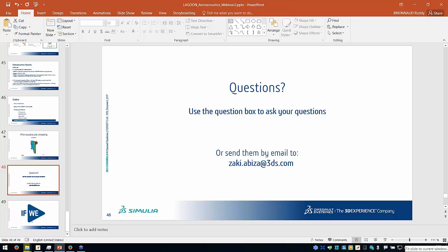So the first question: can XFlow perform acoustics analysis in water? Okay, so I've been speaking about air, for example, but as you've seen, it's very easy for XFlow to adjust the speed of sound. The only difference between air and water is actually the compressibility and speed of sound of your fluid. Typically with air you've got 340 meters per second, and for water you would have 1400 meters per second. So the equation that relates the lattice spacing with the speed of sound is the same, and we just have to change the speed of sound to get another time step.